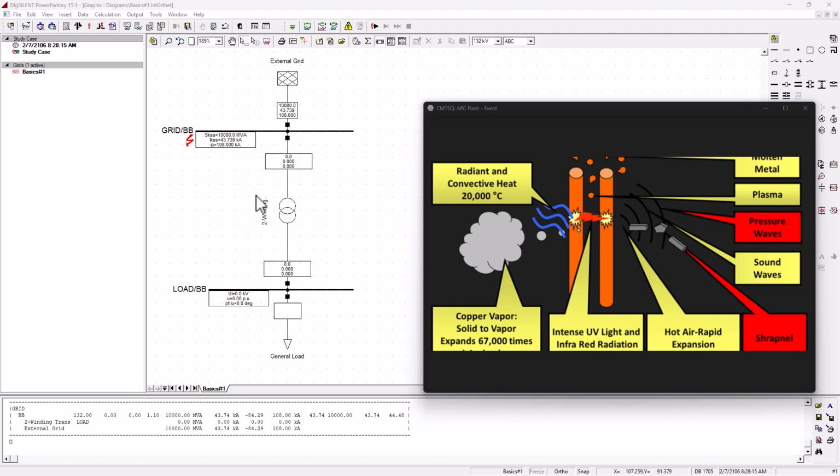I mean, just like in short circuit analysis, you run it so that you can specify your circuit breakers rating, right? The same applies to arc flash analysis. We perform it so that we can quantify the problem we will be dealing with in case it happens.